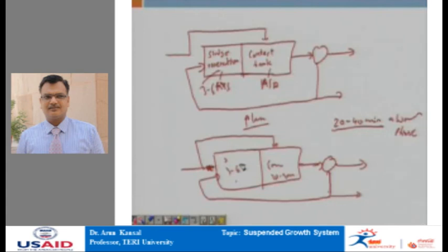Here in the sludge re-aeration, mainly assimilation and dissimilation take place, and here absorption is taking place. This is the secondary settling tank. So, by simply changing, we are converting a conventional aeration tank into a contact stabilization tank, which improves the efficiency of the overall process, or it can handle the increased organic loading.